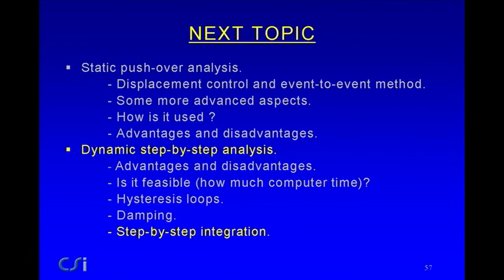And I might say that I found that the two methods seem to agree pretty well for frame structures, but they may not agree quite so well for shear wall structures. And what I've been suggesting people do is to use the Rayleigh damping for shear wall structures rather than modal damping. It seems to work rather better. That's just one of those things which we have to do some more work on. Finally, step-by-step integration through time.